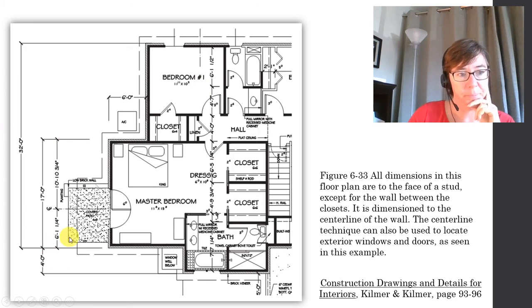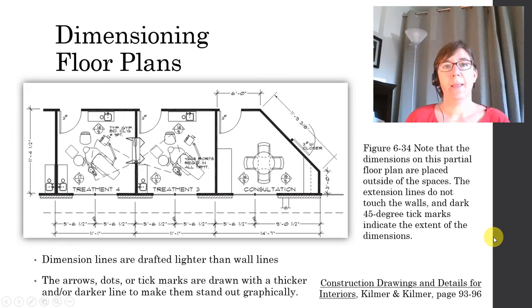Here's one right here. A center line measurement is going to look like this. The line that's actually to the center of something will be a long dash, long dash, short dash, and it will have this CL center line symbol. So let's take a look at another example.